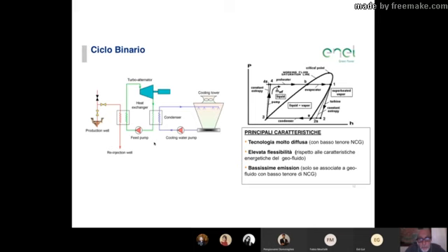The other drawback is that you're going to use and circulate a much larger amount of geothermal water, about 15–20% more for the same amount of electricity produced than a flash cycle. And because of this, you are probably able to induce a much larger number of earthquakes.